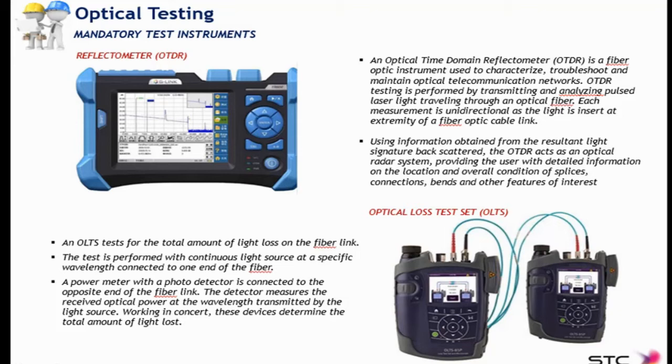So the information provided by the OTDR is calculated. It's not really a measurement like you could understand a meter tape is measuring length. It's not that way of measuring. The OTDR interprets the backscattered light coming from the fiber and estimates, calculates what is happening in the fiber.